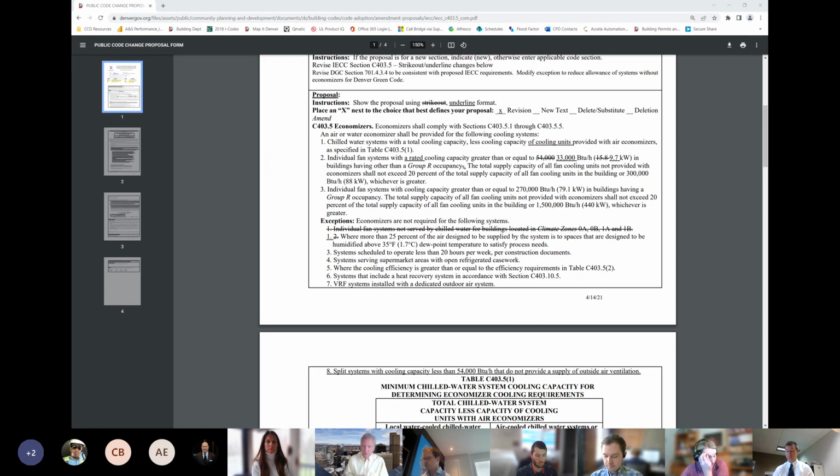It can't possibly be better to spin a compressor all year long than it is to open an outside air damper on a day like this. I would recommend that number 7 be struck, just like it had been up until the 2021 code. John, do you want to talk more about that for number 7 there?